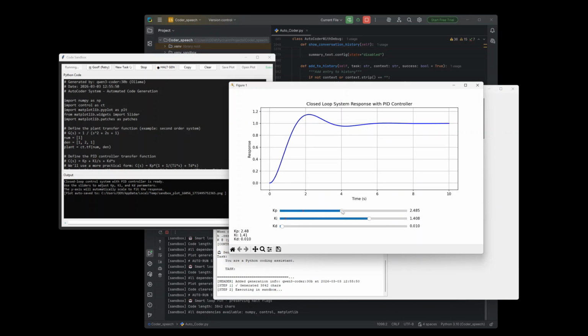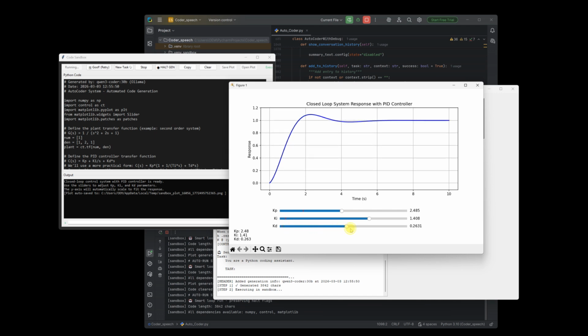So this is back. Now, to get rid of the overshoot, what we can do is increase the proportional gain. Sorry, the derivative gain, derivative action. You see the overshoot coming down. There it goes. Down, down, down, down. Okay. And then, well, you might be happy, but it depends on the overshoot that you want.